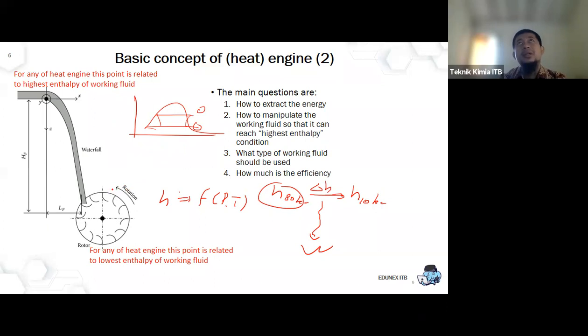For refrigeration, the evaporator is always using this one, the GT valve, so the expansion is isenthalpic. And for water, since the default is a non-compressible fluid, when we expand it in isenthalpic mode, with the same enthalpy, it just does not absorb heat too much.